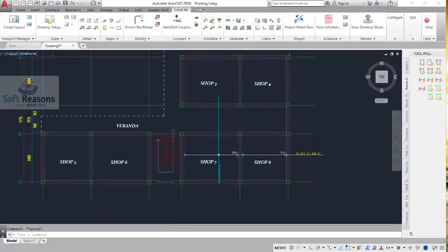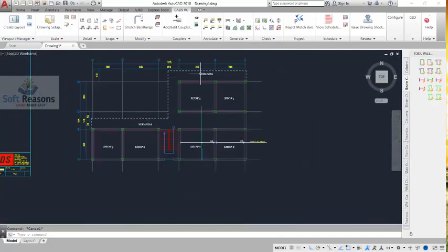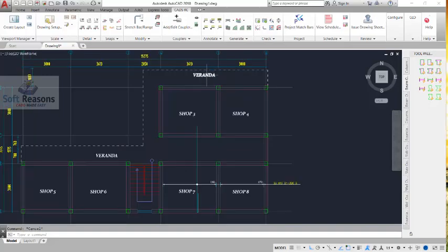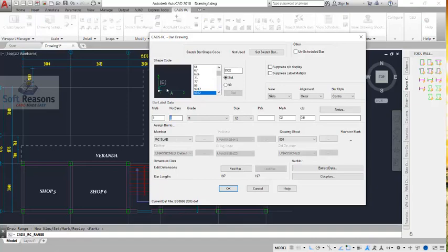Okay, we can't use this one as well, but we want to create a new one. For you to do that, you just have to get over to these provisions and use the third option as well. It is this same bar we are going to be considering, bar mark 9932. It's going to be a bottom bar, right? So key B, you are there.